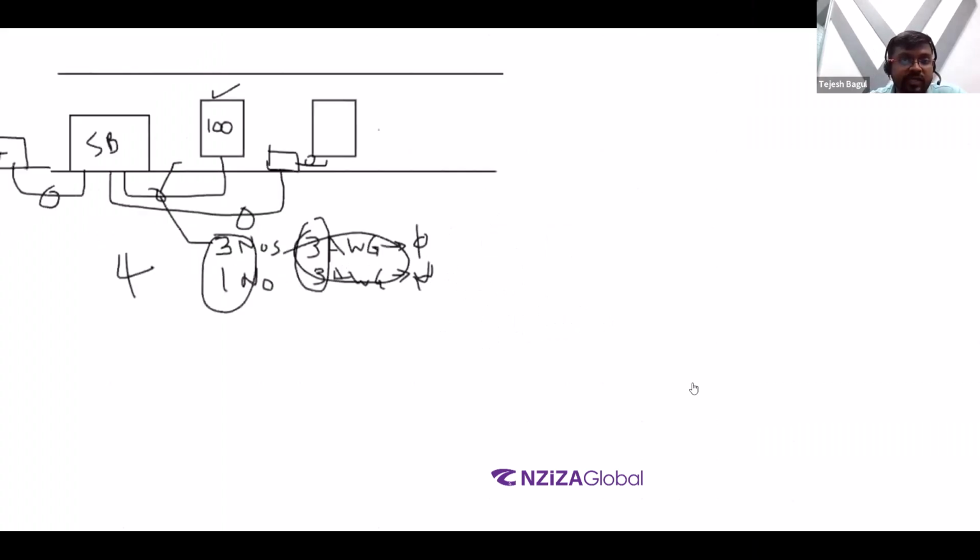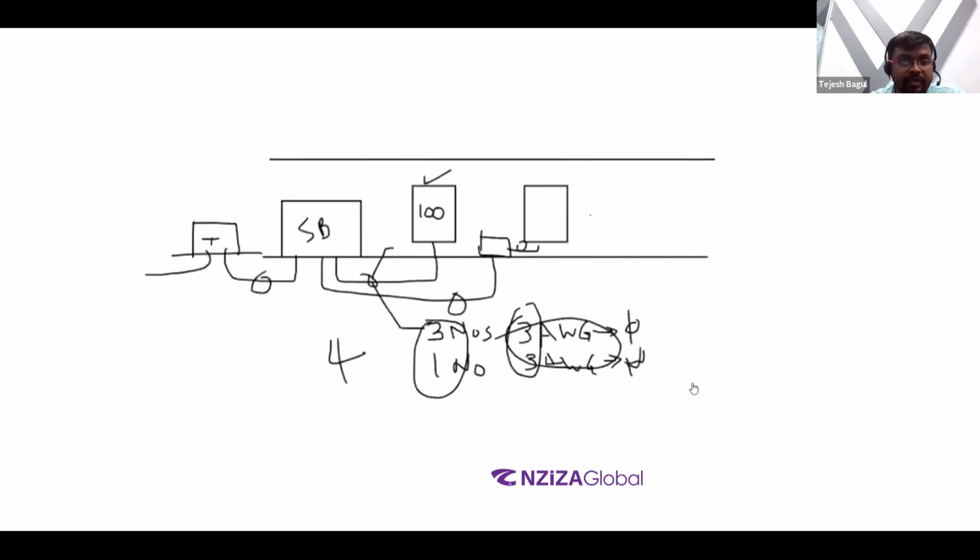But what we are trying to say over here now is this particular conductor set that is coming in will need to be in a minimum 1 1/4 inch conduit. All right. So now this is the cable management that will happen for all of the spaces. Now what happens is when you check for these bigger ampere sizes, it is fine that you note down each and every one.